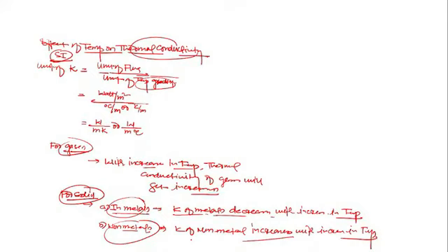This is for solids. Now for liquids. For liquids and gases, there is no such theory, so we should only rely on experiment. As far as liquid is concerned, my dear student, thermal conductivity in liquids is inversely proportional to temperature. It is found from experiment that thermal conductivity of most liquids decreases with increase in temperature. Okay? Only exception is water.